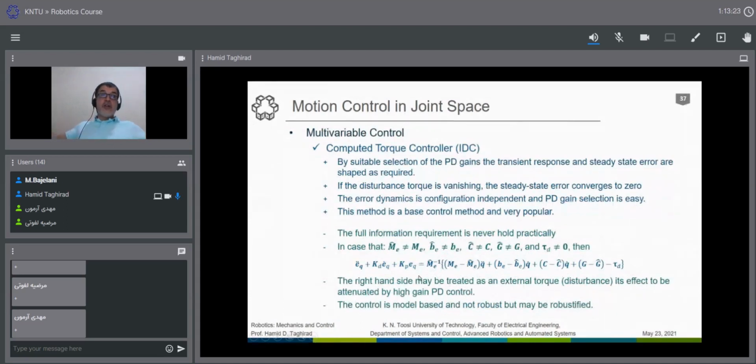This is a long nonlinear term, but it is not necessarily very large valued. Is it correct that M is not equal to M hat? But 90% it is correct. So the term is reduced by 90%. I'm just saying 90%, it's just an approximate value. So we are reducing the nonlinear terms. If we are not canceling them, theoretically, we are using feedback to linearize the system.